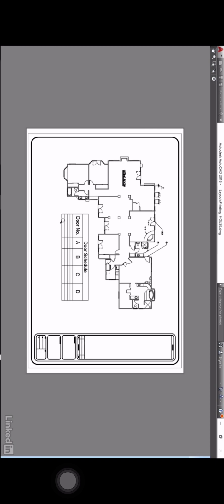You're saving all of these settings, this D-size DWF page setup, so that you can apply it to any layout you want to. I'm not going to change any of the settings here, but if I click on preview, it gives me a little preview of my title block, and you can see the viewports layer is set not to plot because it's not showing in this preview. I'll right click and exit, and it takes me back into the page setup dialog box. I'll OK that, and it prompts me saying that the page setup I just edited, which I didn't, I only looked at it, but it thinks I've edited it. So I'm going to say yes just to update everything.